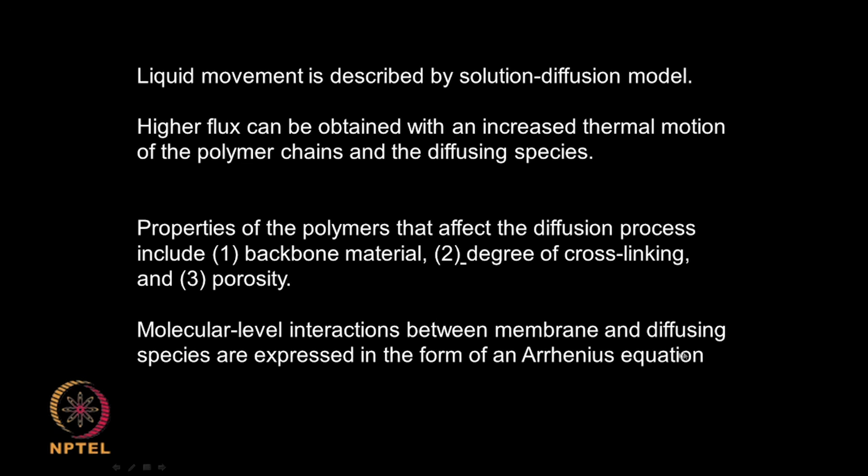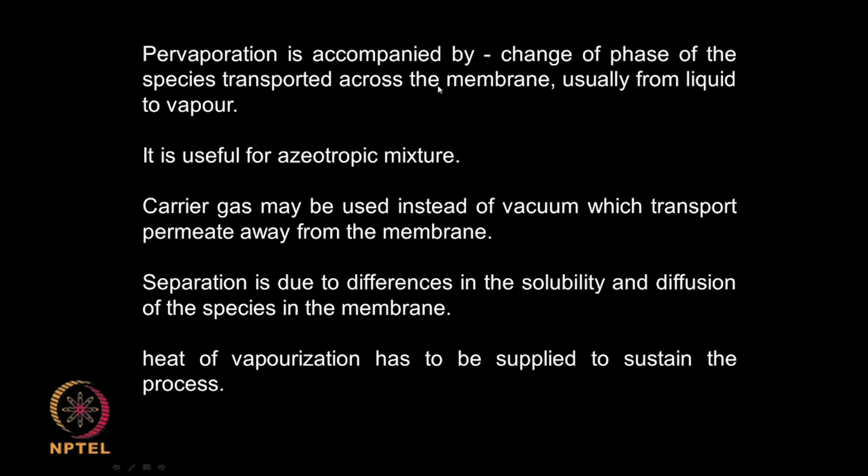So, it is generally expressed in terms of the Arrhenius equation. Pervaporation is accompanied by a change of phase, you need to remember, because you are heating, so you are forming vapor, then the solute goes through, and on the other side the solute is condensed, it becomes liquid. So, it is much more useful than azeotropic distillation. Sometimes you can use a carrier gas also, so that we can drive this.